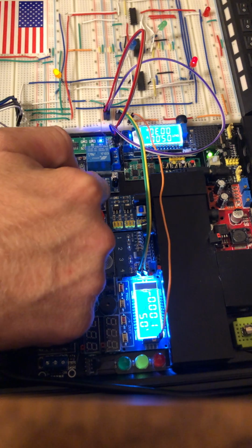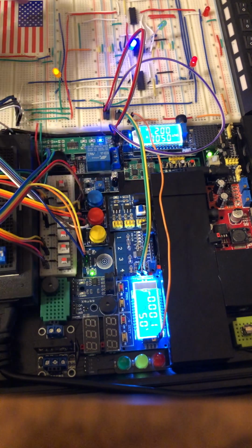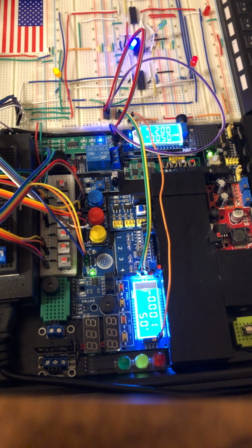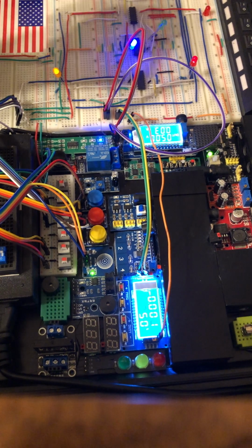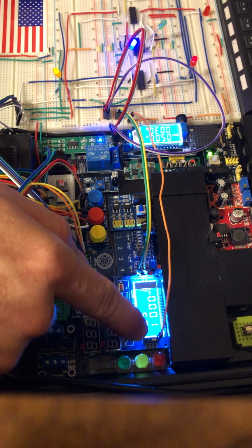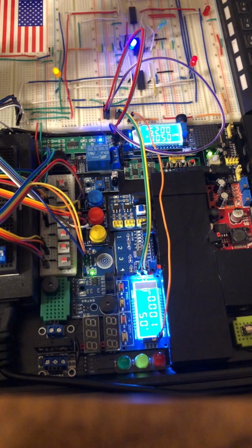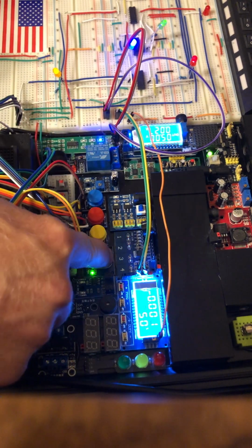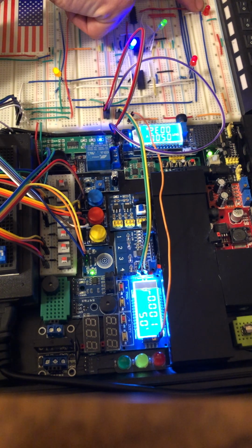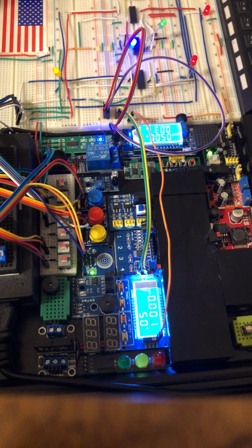Then we're going to have our third push button, which is going to go to our next AND gate, and you see that with the blue light LED there. Now this fourth push button is our last one, and what that's going to do is send that 1 all the way to the other AND gate, and then that's going to flash on and off with our 0 and 1 coming from our pulse. You'll see that now. You see the last LED came on, and now we have our last LED flashing on and off, 50% on and 50% off.